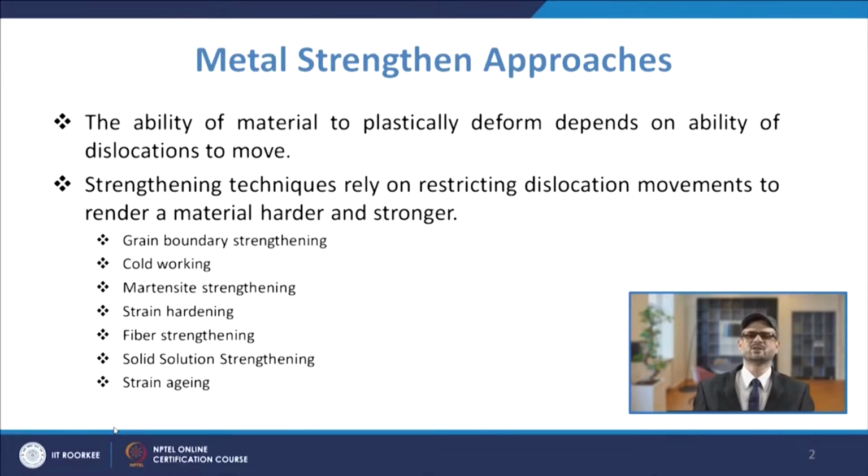Solid solution strengthening is based on the concept that when we make a solid solution, you will have interatomic distances, or interatomic voids in fact, and you try to alloy with a material which is much smaller in size, but its size is more than the voids between the atoms.